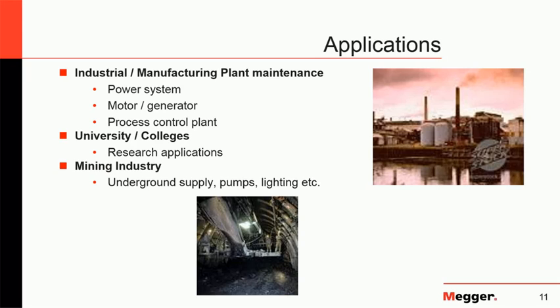But let's say we have a problem in one of the junctions in that bus bar, and the resistance changes to 100 micro-ohms. One may think that change is not significant, but at that level of current, the power dissipated will go up to 14,400 watts.